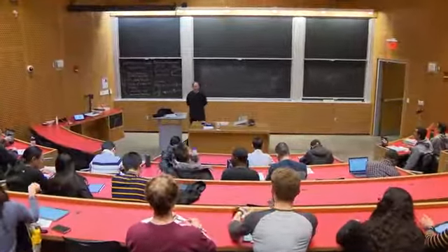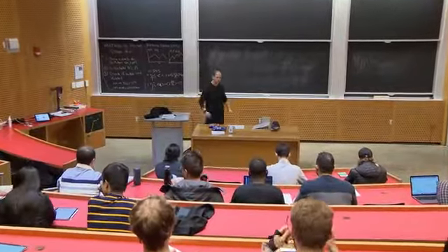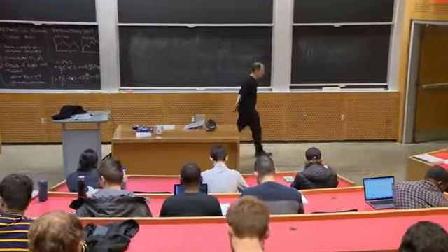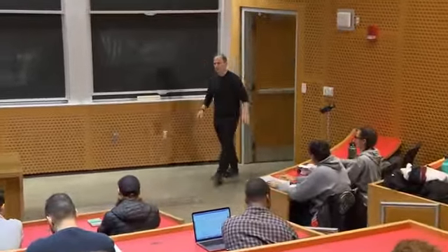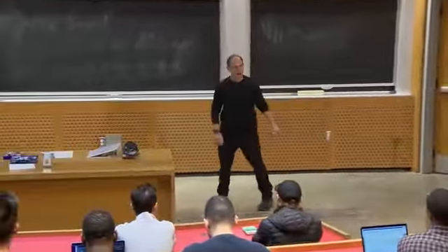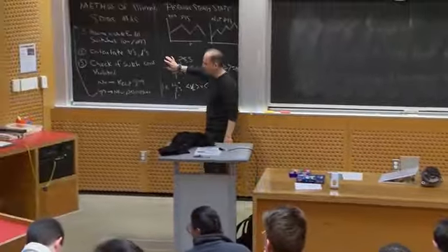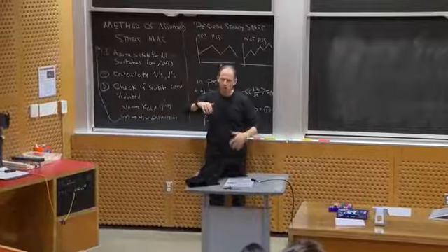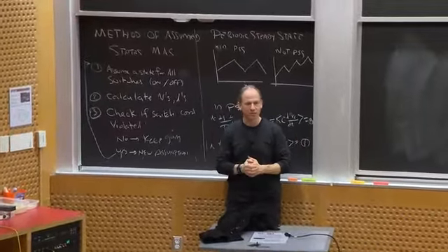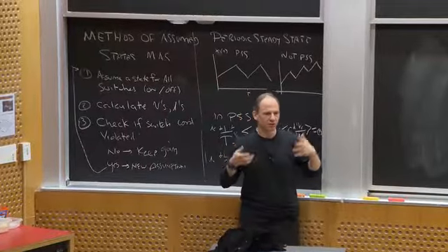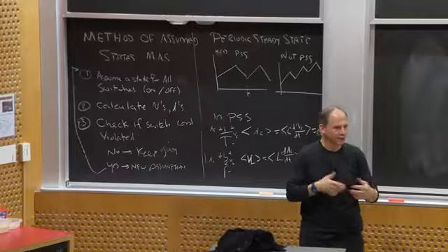So just as a brief reminder about where we started last class, we started to introduce some tools to think about switching circuits, and in particular, techniques for time domain analysis of such circuits. The first thing we said was that if we had diodes in a circuit, we can't really tell them when to turn on and off. They turn on and off based on what's going on in the circuit. So we came up with this notion of the method of assumed states to instantaneously figure out what's going on with an individual diode of the circuit.